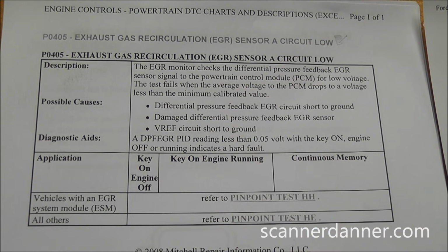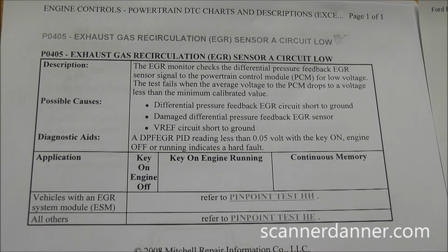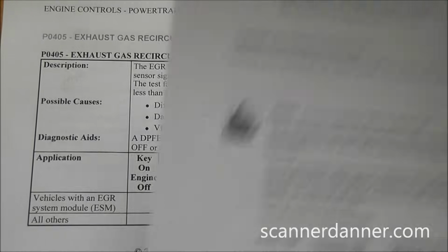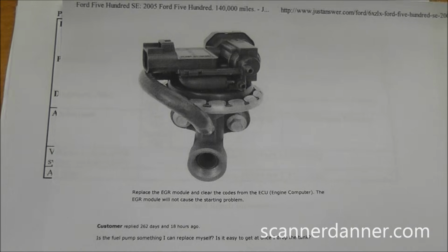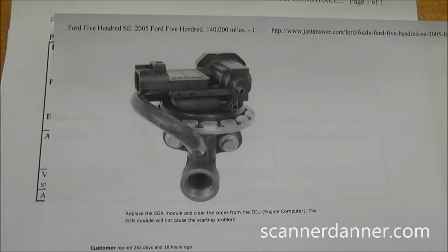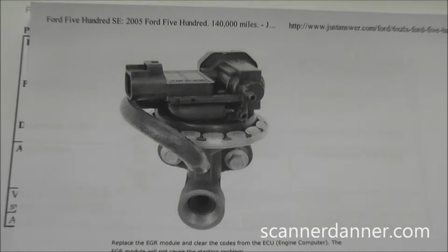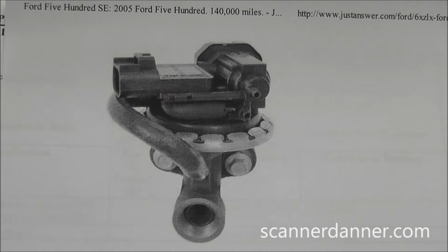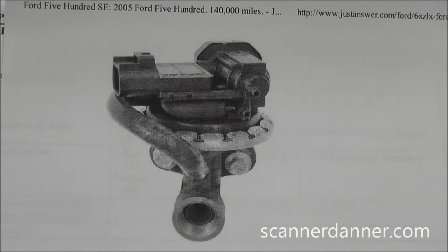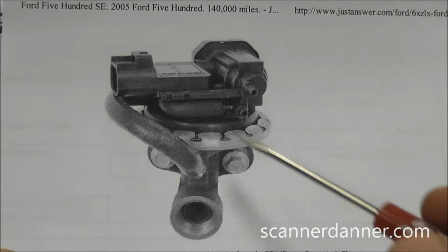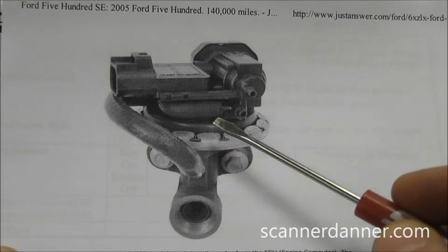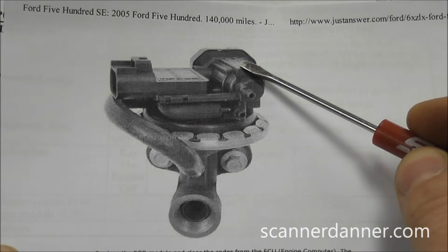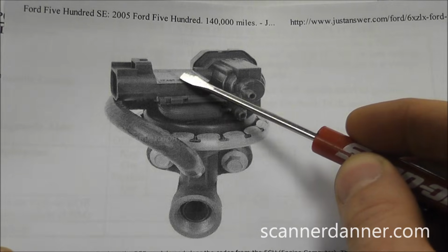In fact, I was a little bit unsure. I had an idea because I've run into these on some newer Fords, and this is actually what Ford calls the EGR system module. What they've done on this design, this is the newest design, and all I did was Google image EGR system monitor for a Ford, and I got this picture. What they've done is they've taken the EGR valve and they've added the EVR solenoid and the DPFE sensor all in one unit.